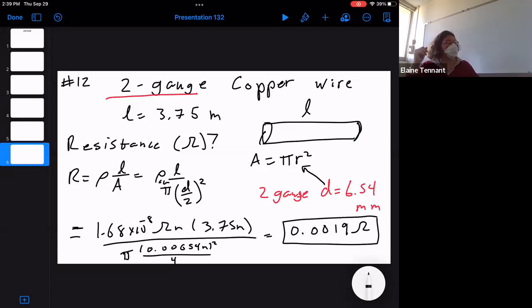They have to wire from that power source out to each of these things. So they definitely have wires that are longer than 4 meters. And if for every 4 meters we get 0.002 ohms of resistance, that's going to build up quickly. We will talk about how to deal with this when we start talking about AC circuits. But just be aware that there is an issue here. Sound good? Okay, cool.